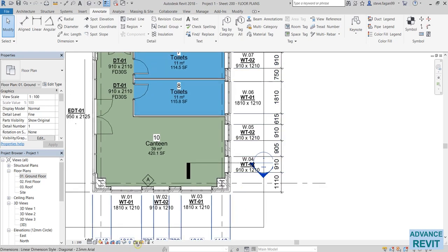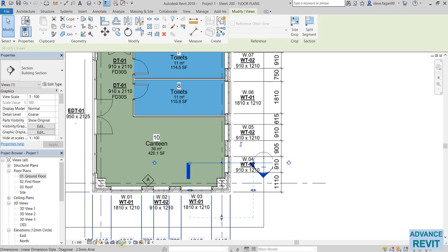So what I'm going to do is come down to my visual controls down the bottom here. I have two tools. First, how I can hide certain objects, and next is where I can reveal them. What I need to do first is select the object I want to hide, select the glasses, and I have four options there.